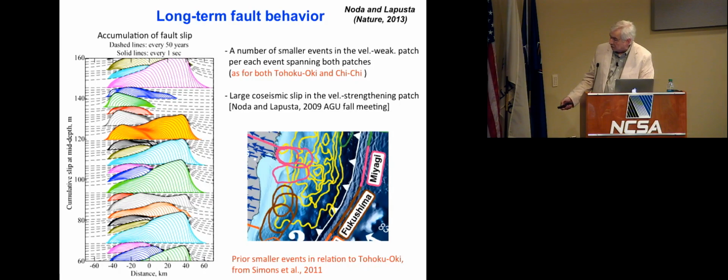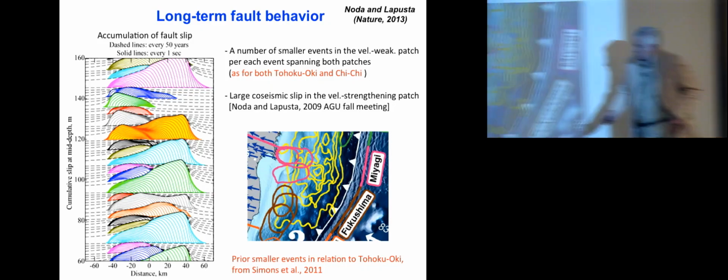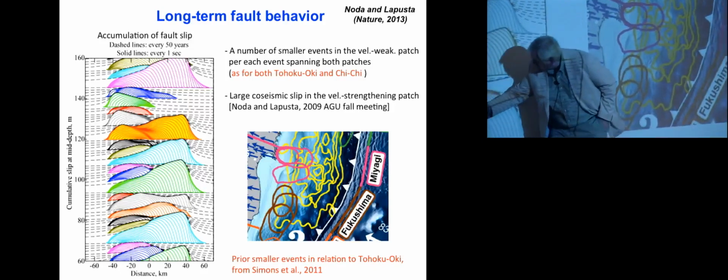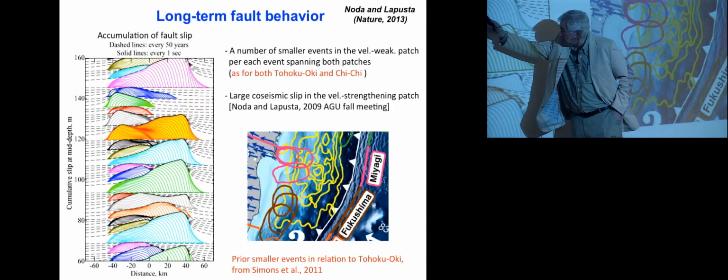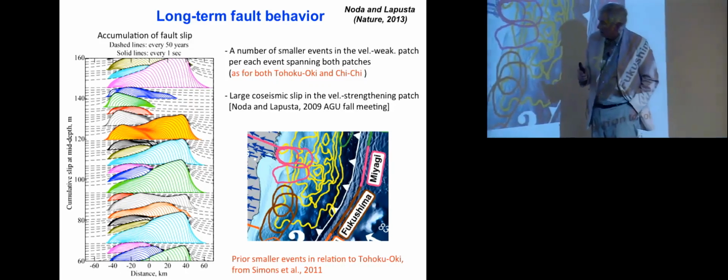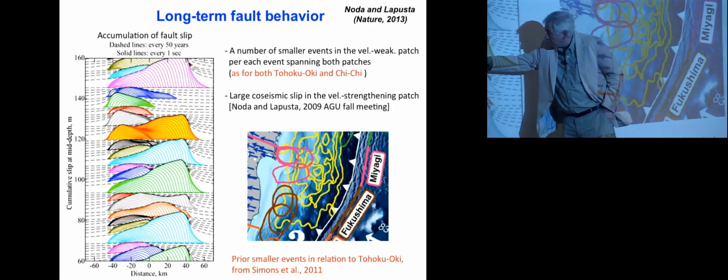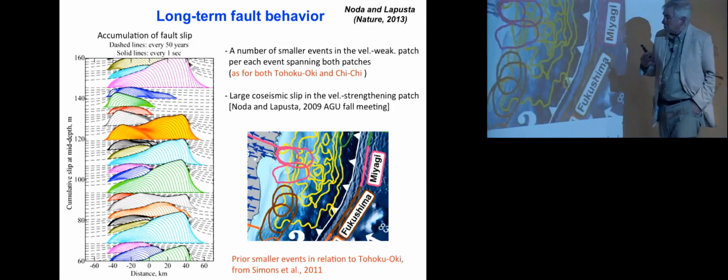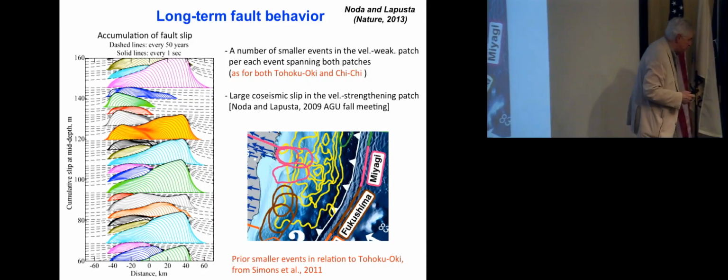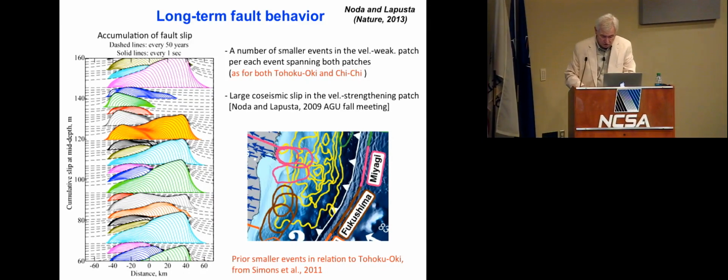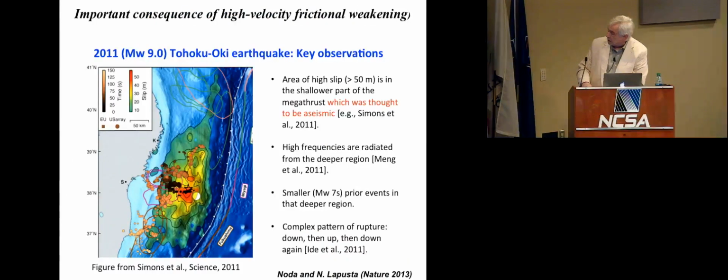This is distance along the rupture zone. And the idea is that you have frequent earthquakes in the south. You're seeing slip versus distance here. So these little bulges are the slips in individual earthquakes that get nucleated. And most of these earthquakes start and stop in the south, but occasionally there's enough stress to activate the northern part, and the northern part is much more susceptible to extreme dynamic weakening and creates big events like the 1999 Chi-Chi earthquake. At least that's their hypothesis. I think it makes some sense, but of course it's premature to say for sure whether that's what happened.